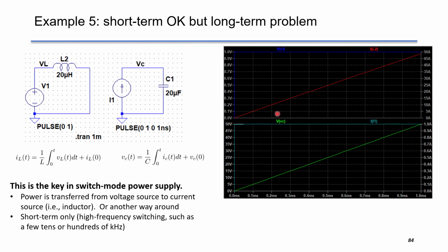So this is the transient simulation. If we put a 1 volt step over the inductor, the current will build up and ramp up over time, given a constant slope. This slope is defined by 1 over L, and also defined by the applied voltage, V.